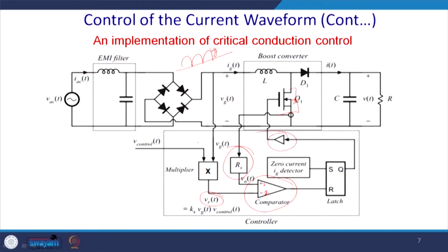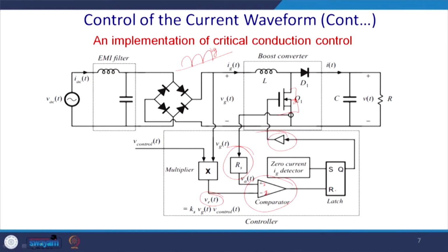This is a buffer, you know. Why? Because you can easily implement this circuit. Of course, the chip is available to you, or by discrete components. This is the unity feedback op amp, a voltage follower, and of course, you are going to give a resistance to it, because it is required to sink a certain amount of the current that has to be provided by the buffer, because these devices cannot provide this much.